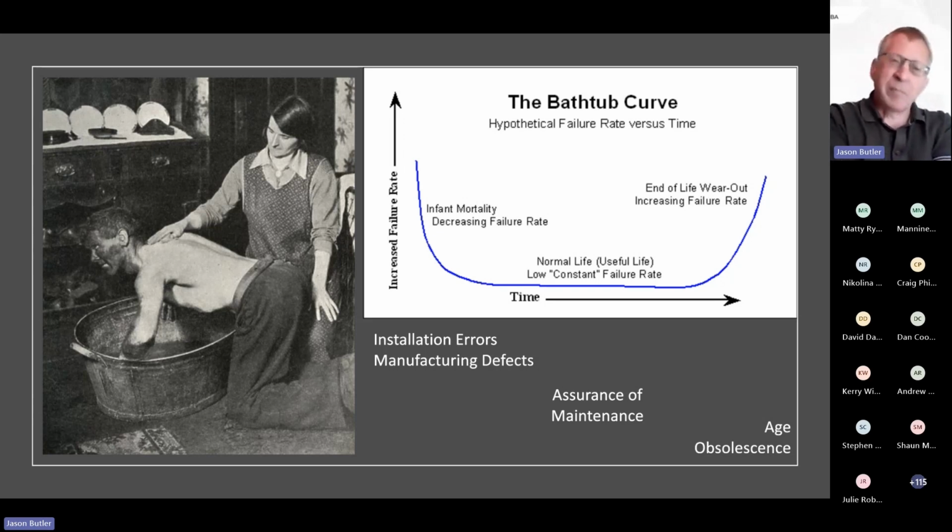You can't just pop down to B&Q or Screwfix and pick it up. It's 3 months if you're lucky, 9 months if you're after a substation. So again, it is giving you that early warning and monitoring the situation. And when you find something, when you find PD, the question is, well, now what? And then it's increasing that monitoring to track the rate of change.